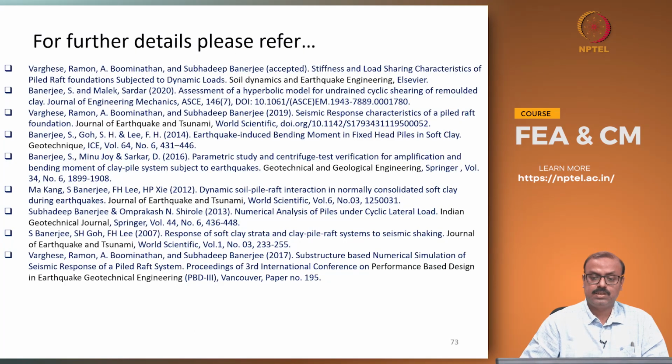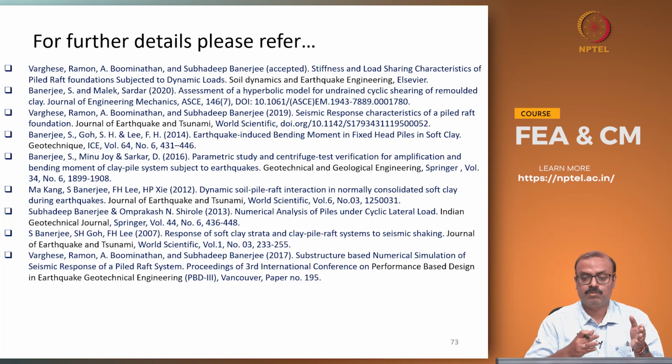So, in today's lecture we have seen an overall description of the usage of finite element software for a few geotechnical problems, and how to go from plane strain to complex seismic response, with the different nuances of modeling from the meshing to the properties, how to handle drained and undrained behavior, and where to use the regular pile elements or a hybrid type of pile element for different purposes.